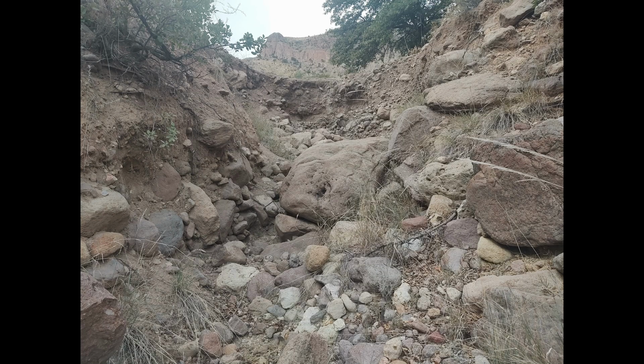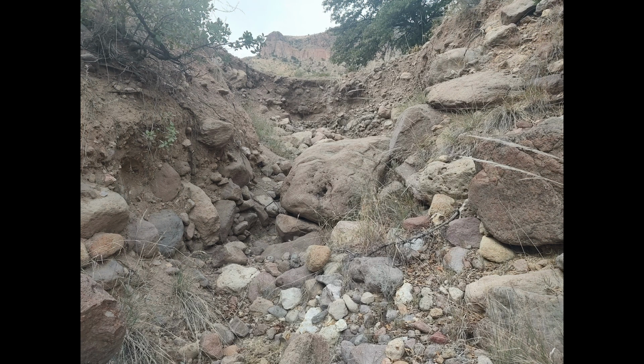The flow of water in the failed spillway caused head cuts with a 7-foot-high vertical face to form. The shear stresses were so high that large boulders cascaded down the mountain with each storm. The eroding spillway would be nearly impossible and very expensive to repair.